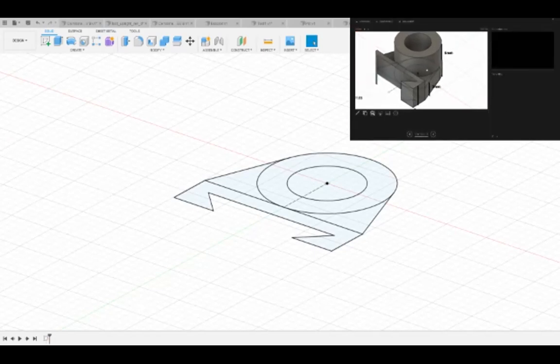Yeah, this will do. So this one's a little bit more complicated in terms of making your extrusion correct. Since I had mentioned prior that you can actually select individual contours, you can make 3 sketch features that all do 3 different things. So we have this little part here. So for example, this part in the center.